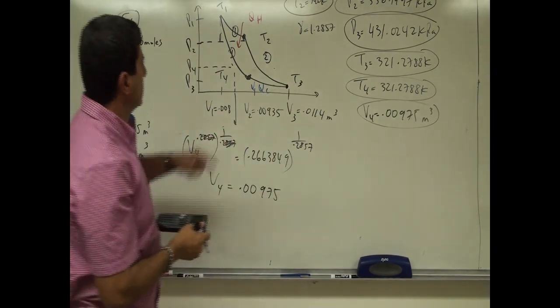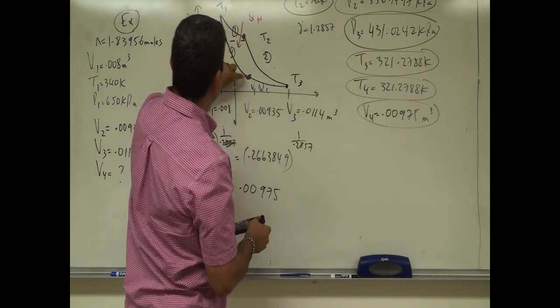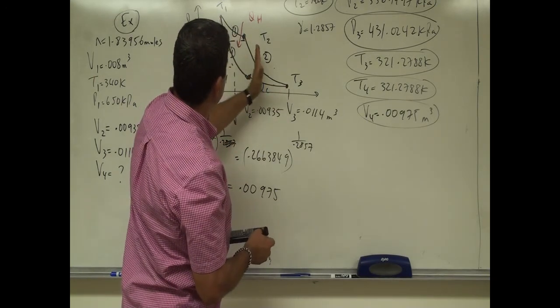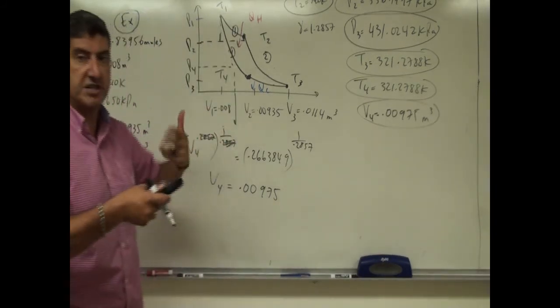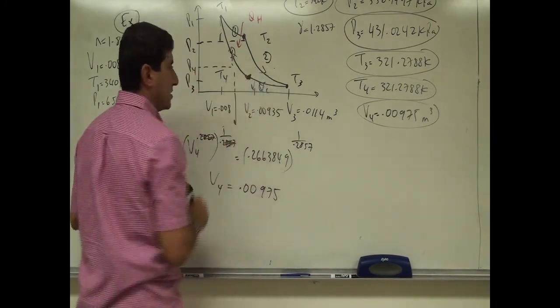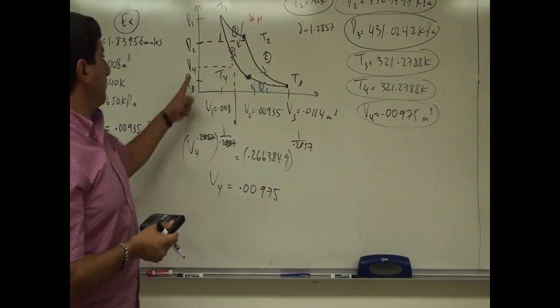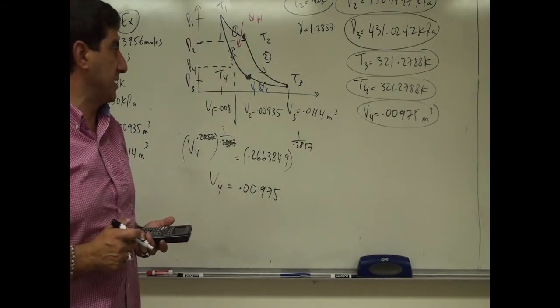Something like that. So you see, this is isothermal, adiabatic, isothermal, adiabatic. This V4 is slightly to the right of the V2, which is possible. It just depends on the numbers that were given, you see. So we're going like this, like this, like this. Then what's left to do? How about calculating P4? And then once we did that, we get the answer.